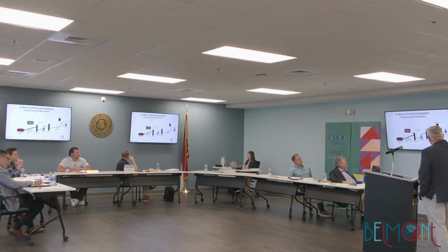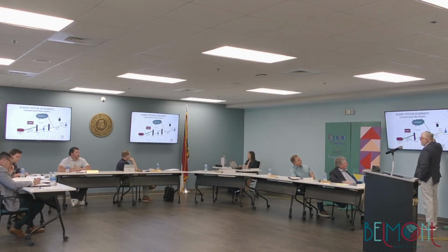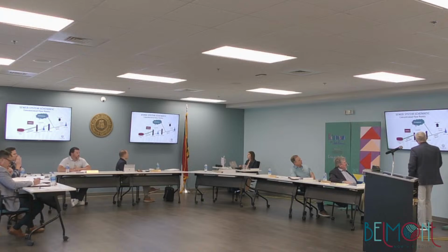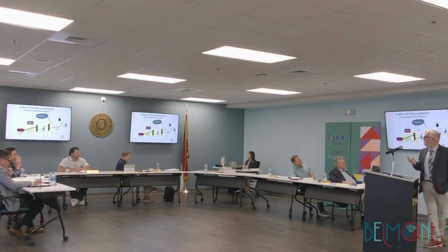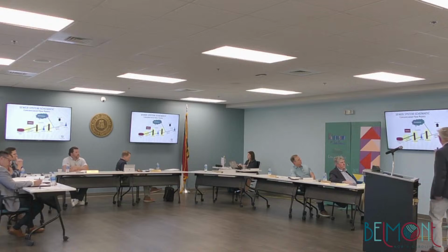So I want to hit on this just really quick, as I mentioned before, where the development is actually occurring. You can have impacts right at the spot where it connects, right? So these are your resident service laterals, manholes, these are lift stations that pump to another manhole to go to another lift station. But it's not just right here that we're looking. Each one of these highlighted areas are those concentration points. That flow is going to end up there. Rainwater getting in the system, it's going to end up there. Tributary flow, actual wastewater flow, it's going to end up there. It's going to become that concentration point. This is generally where you start to see your issues show up.